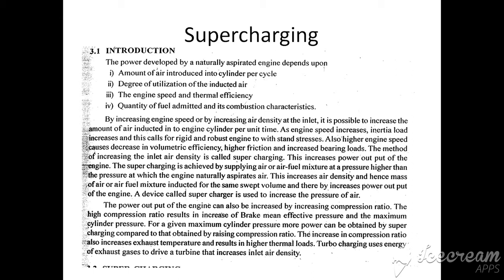Okay, so this is about supercharging. And the power output can also be increased by increasing the compression ratio. So by increasing compression ratio, the brake mean effective pressure will increase and the maximum cylinder pressure will increase. Okay, but this leads to higher exhaust temperatures and higher thermal loads.